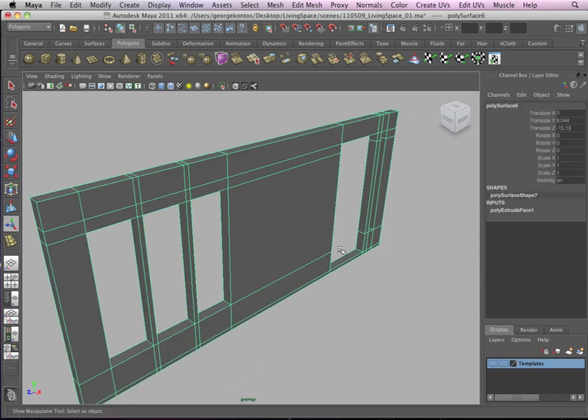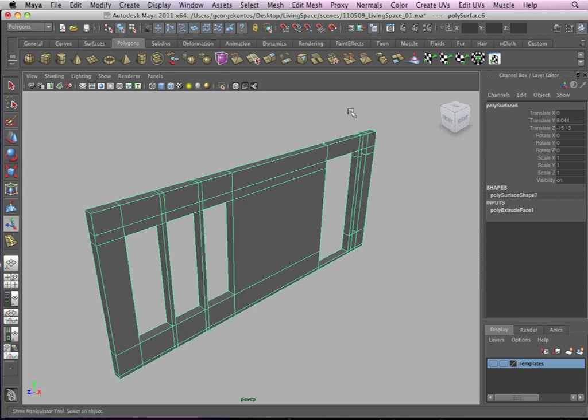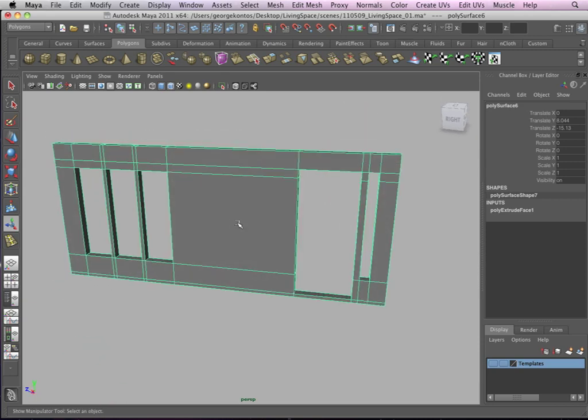So remember the number you added to the extrusion, because if you extrude another wall, you want to extrude the same thickness. Mark that number down, so you know it's 1 or 0.5, because sometimes you will delete the history and that information is gone. You don't even know how much it is. So whenever you extrude a wall space and you configure a unit, make sure you use the same unit for everything else.